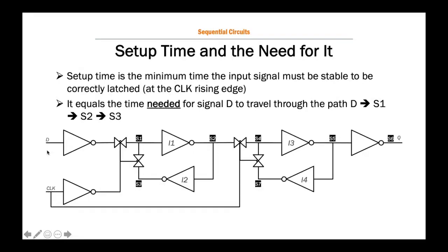If D comes late, because of noise and, as we mentioned, the propagation delay and all the delays, clock to Q, propagation and all of that, so your signal is coming late, coming at T minus 1, then you are risking that the gate is shut and this one is open. This one is shut, without properly sampling the value that you were looking for.